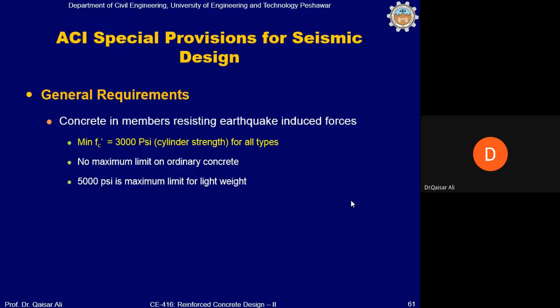And you will see that the construction or detailing of the SMRF will become very, very difficult, demanding and challenging, because in the beginning we have taken an advantage of taking R equal to 8.5 and thereby reducing your base shear. On one side you take this advantage by taking R very high, equal to 8.5, the highest value in the UBC, but then the code wants to make sure that you produce a special moment resisting frame.